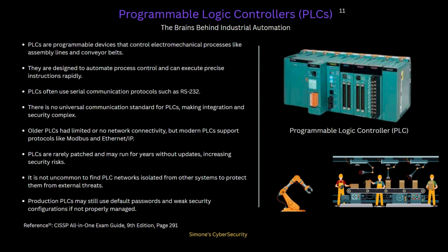Traditionally, PLCs communicated with these field devices using serial protocols like RS-232. But today, newer PLCs often support protocols like Modbus or Ethernet IP. And in our lab section, in section 8, I will show you how we will exploit this Modbus protocol and manipulate the PLC. Even though the newer PLCs support these different communication protocols, there is no universal communication standard for PLCs, which makes integrating and securing them more complex.